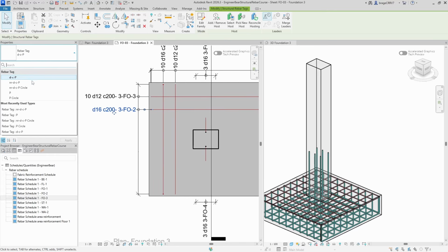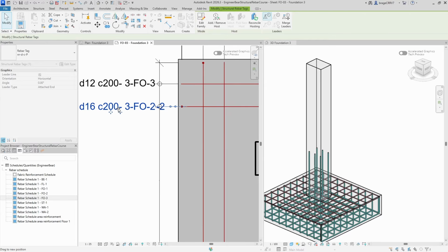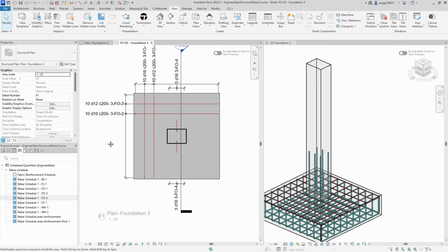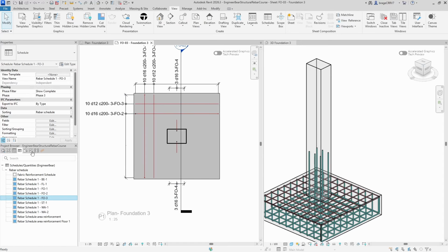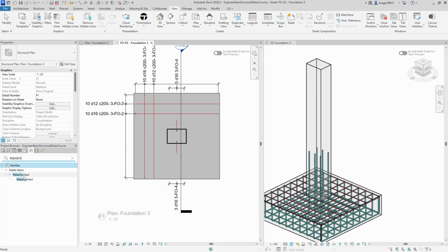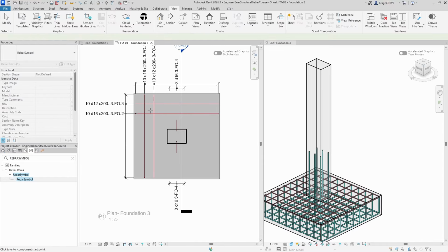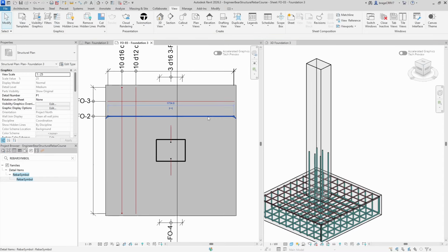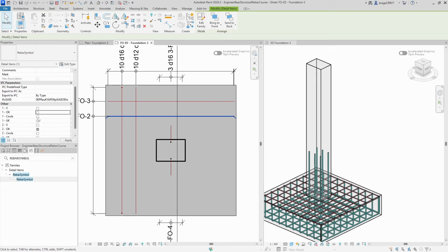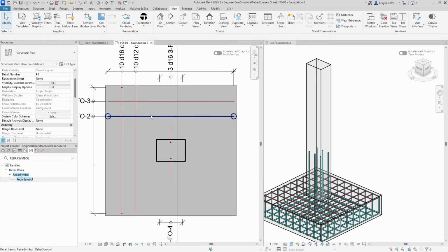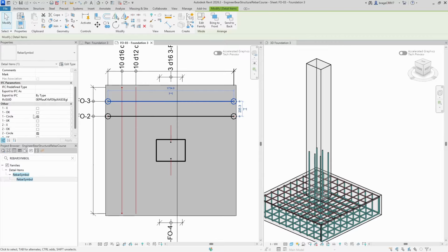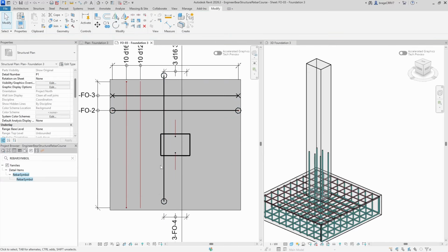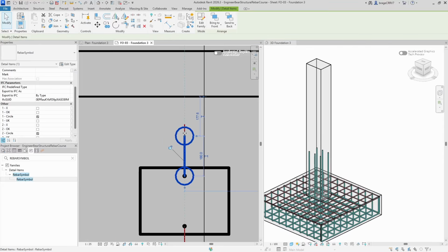I can also set a rebar dimension line and tag a rebar in two operations using the tag tool and the annotate tool. In Norway, we do use symbols to represent the rebar shape and layout, so I have created a family that contains the necessary symbols that can be toggled on and off depending on the rebar. Again, there is some manually tedious work to be done. The symbols make the shop drawing a little bit nicer and easier to read.